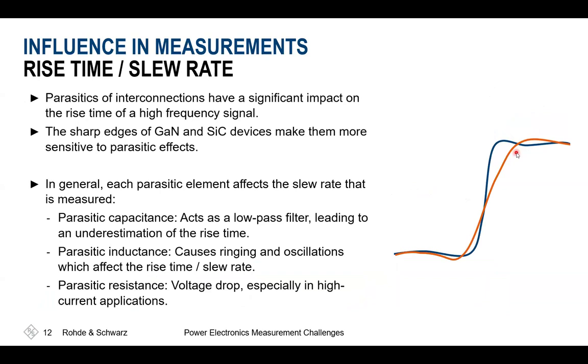So the major question always will be, if you're measuring a slow slew rate coming out of your semiconductor device, then you would expect from the data sheet of the switching device, this will be affected by the dispersion coming out of these different effects that I've just discussed. Basically, you're always adding low-pass filters by the caps.